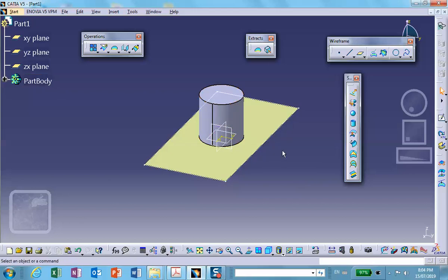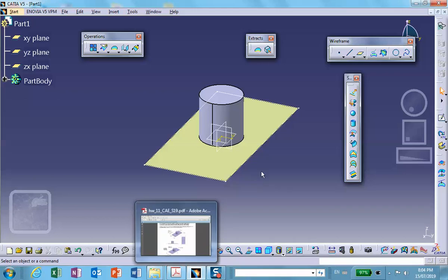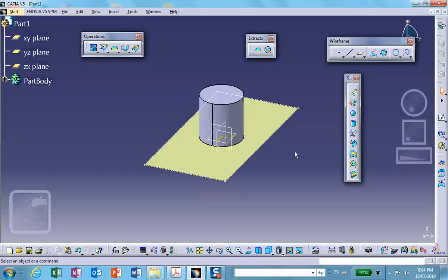One should be taking into account the thickness of the shell here, and dimensions should not play. But what I assumed here is that the thickness of the shell can be, not that it can be ignored, you're going to be using it, but when it comes to these dimensions, these are nominal dimensions, so we just ignore the variation of the thickness. So half of the thickness up, half of the thickness down, but we are assuming that thickness is small compared to the overall dimension, and therefore we're going to ignore that.